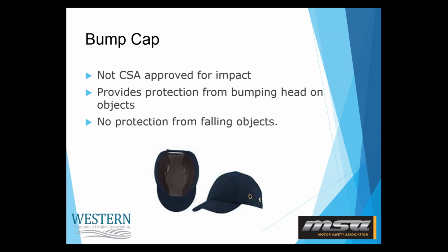Bump caps aren't good for working under cranes or overhead hazards because they don't provide you any type of impact protection from falling objects. And when we are storing our bump caps, a lot of these types of products, keep them stored in clean environments away from extreme temperatures.